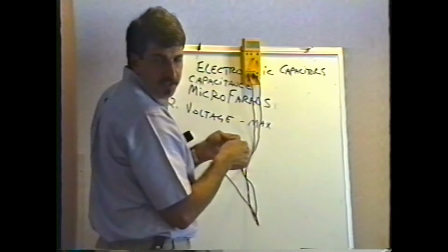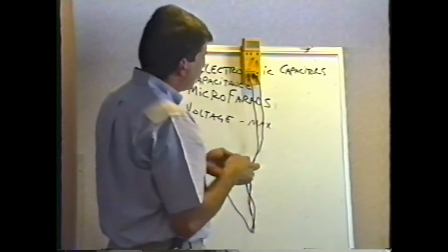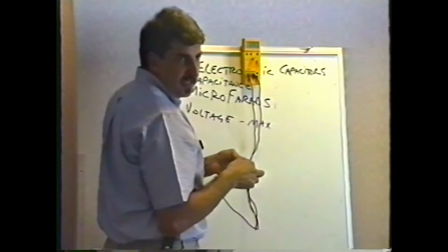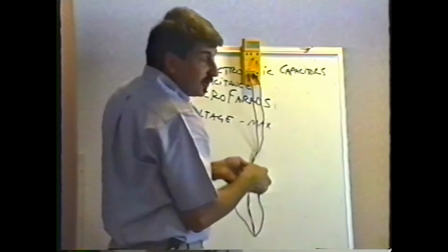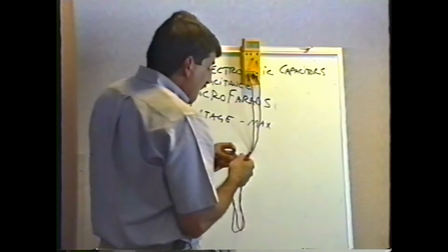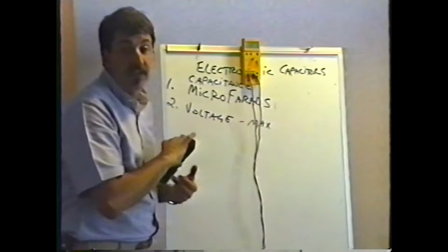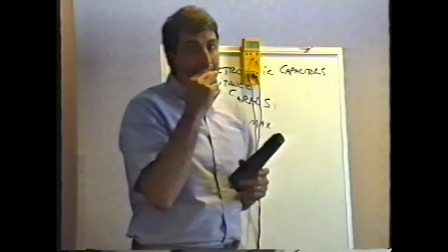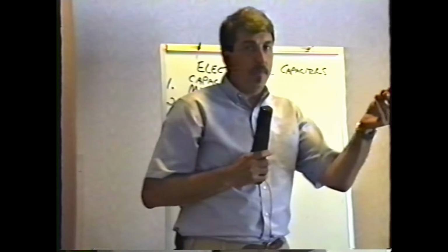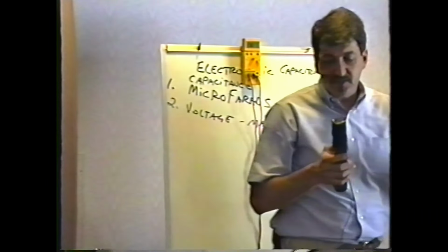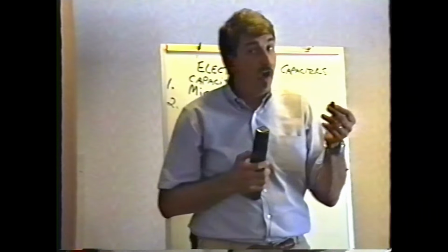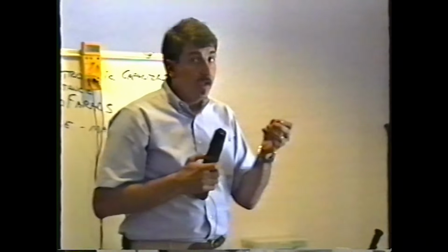The meter's changing. You can see it's increasing in numbers. Well, obviously, this capacitor is taking a charge. That's what they say. Well, it's taking a charge, it's good. Well, in a way, they are correct. Yes, it is definitely taking a charge. But unless you have another one of the same capacitor and a stopwatch so that you can tell how long it takes to charge up, you don't know if it's the correct value. In other words, a 100 microfarad capacitor will charge up just like a 1,000 microfarad will.